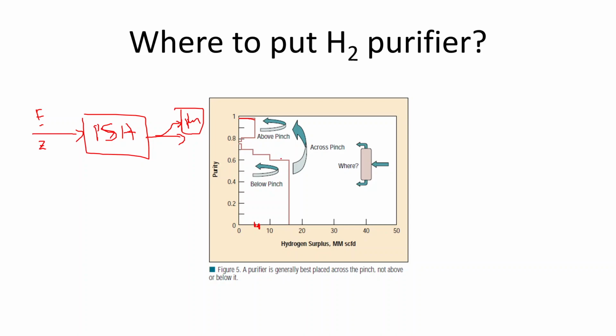So then you can say, okay, for example, if I mix this stream, because this is the lower stream, a low concentration, with that stream, you have this amount of flow rate with a certain concentration somewhere in between, somewhere here, and then the amount of flow rate of hydrogen with this specific concentration. So now you can solve this and put it into the PSA, and then you know that I don't have to design for a very pure hydrogen. I could design it somewhere here, with a little bit more flow rate over here, yeah.